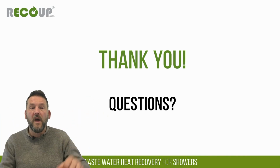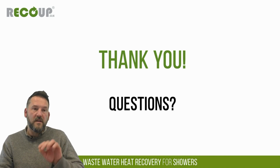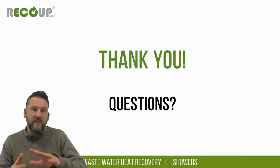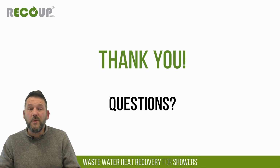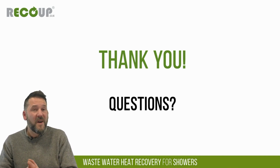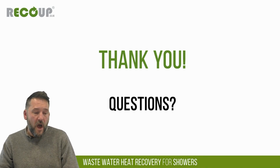But if that was installed as System B or System C, slightly less efficiency, but it gives us more headroom, so up to 22 to 24 litres, so 2 11 litre per minute showers, which is a pretty high flow rate for new build these days, in all honesty. So, two showers at 9 litres per minute would be common. Certainly that can be coped with a single unit.